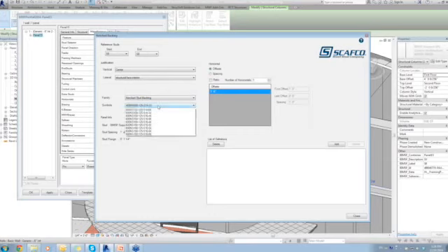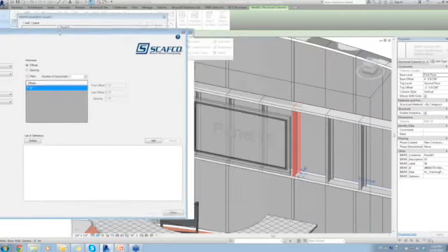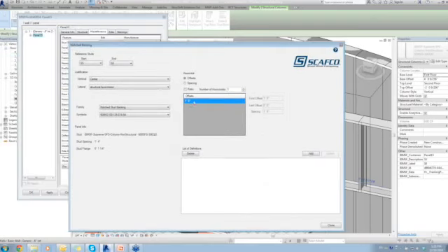Use the stud, and then as I showed you before, all of the available members I can select. So I'm going to take this 600 notch stud, the designation of if you're already ordering from SCAFCO, it's very familiar for you, the spacing at 16. I then specify where I want this piece of track in relation to the bottom of my panel. I'm going to say 2 feet off the bottom. I just need one member, that's fine. I add the entire collection I've just made to this panel.